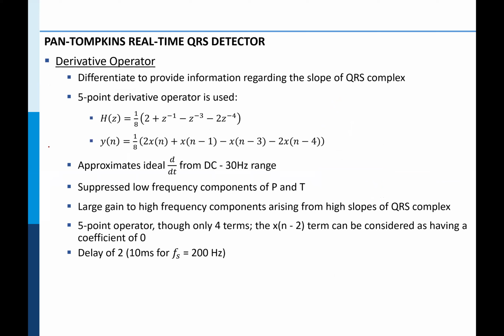Now, the second stage in the Pan-Tompkins algorithm is the derivative filter. And you have seen this derivative operation before, including in one of the labs. The idea of the derivative filter is really to enhance certain frequencies. So it's kind of a high-pass filtering operation. Typically, mathematically speaking, a derivative filter is one that enhances the slope in the signal, okay? Because the slope in a time domain signal corresponds to some kind of a relatively high frequency activity, and that really gets enhanced through the derivative operation.